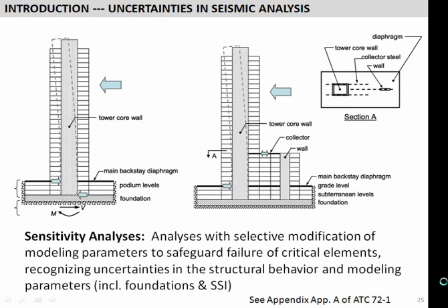Because ultimately, the code doesn't relieve you of that responsibility, even though it gives prescriptive rules. And as I've mentioned, practitioners might hate this because you've got to run more time history analyses and wait a few more hours. So it's a matter of using your judgment in terms of when things are really important, when there might be a dramatic difference in the calculated values due to the assumptions made in your model.